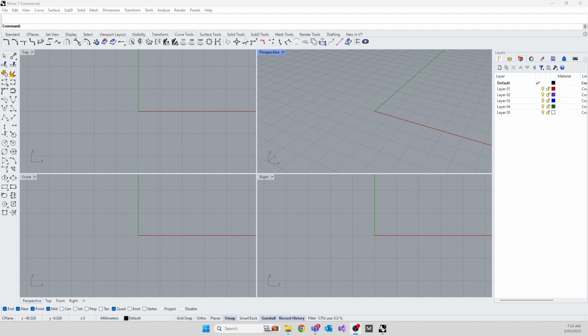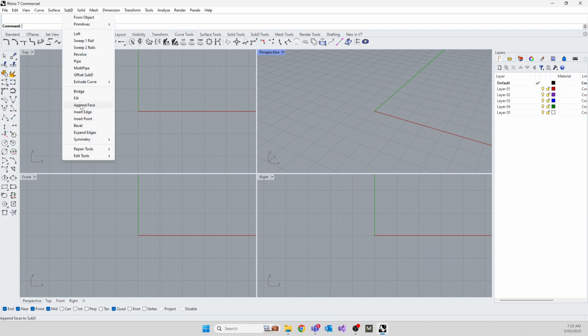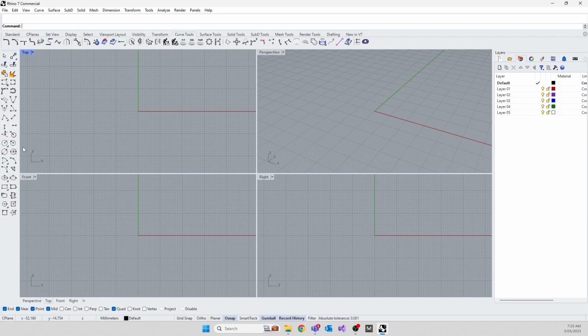Okay, so the interface for Rhino can take its commands in the form of a command typed out onto the command line. The command line is up at the top here, so you can type out a command. You can find the icon for a command, or you can find a menu item for the command. In the case of circle, you can find all the different iterations of a circle. Any icon that has a little triangle on the bottom of it, hover your mouse over it and click the little triangle. If you click the triangle, all the different versions of a circle will come up.